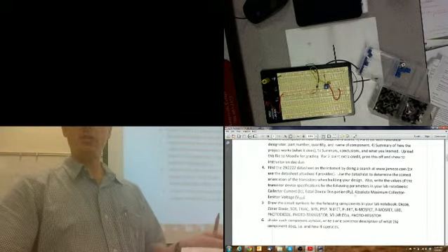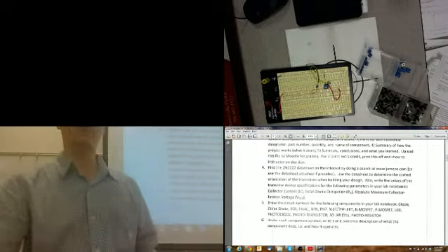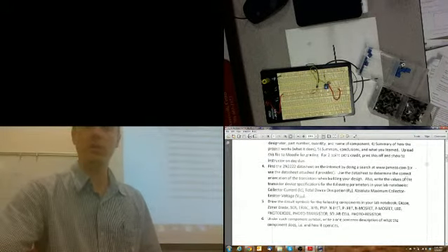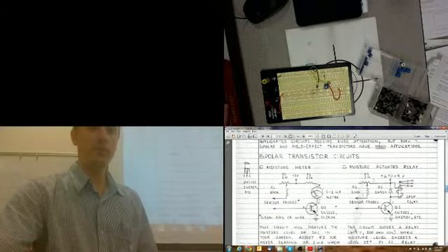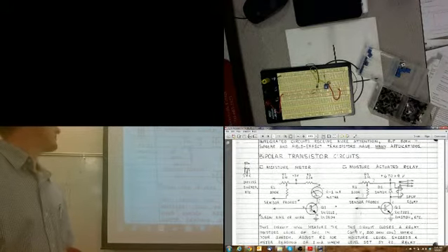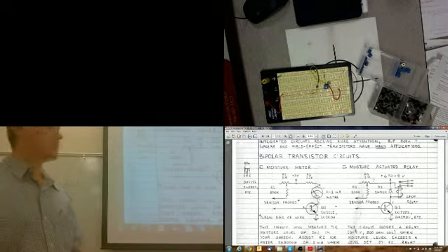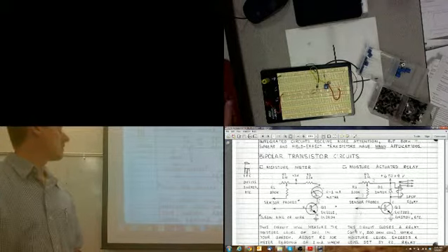And for the data sheet, I put the data sheet in the back, just a one-page data sheet. But if you want more data sheets, we have this transistor data sheet kit that I made. You can go to the 2N2222 and find all the information for that data sheet. Part of the hardest part about it is figuring out the orientation of the part and how it goes in there. You can see here on the screen that if you look at the transistor from the flat side of it, it's from left to right, emitter, base, collector. And those are marked EBC on the schematic diagram. EBC. Makes it a little bit easier for you.